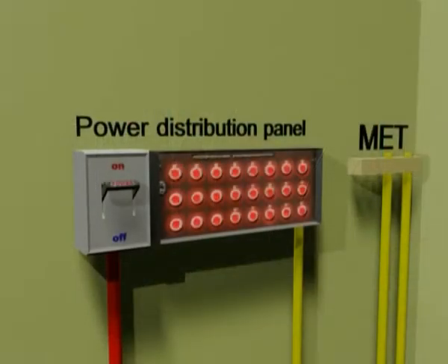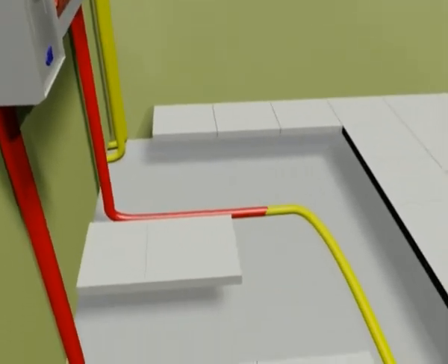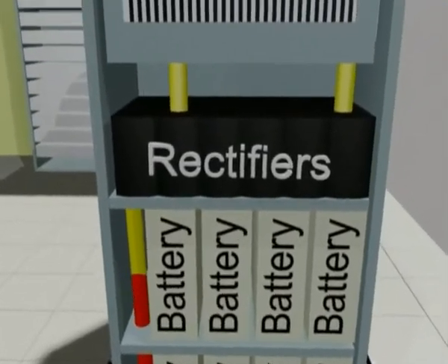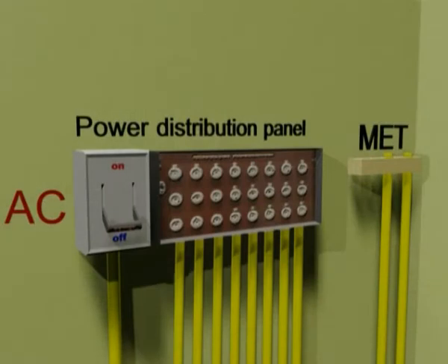As a final safety precaution on the AC side, each of these AC distribution cables is connected to an AC distribution circuit breaker, dimensioned to guarantee safe AC supply to the rectifiers. For easy handling, these numerous AC distribution cables are all distributed from a unit that carries the AC distribution circuit breakers. This box is called an AC distribution unit.